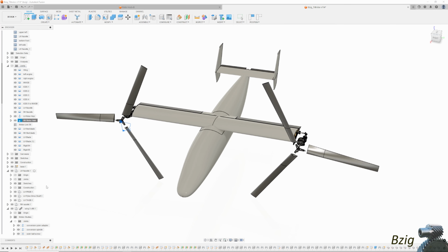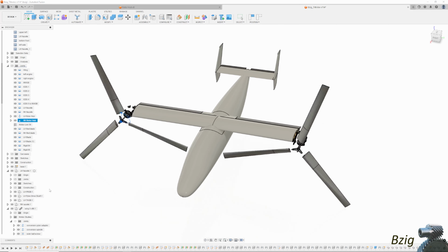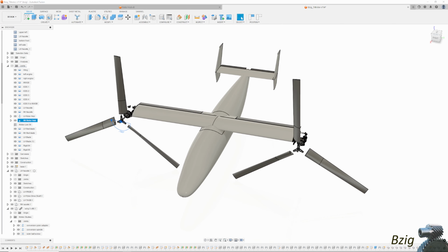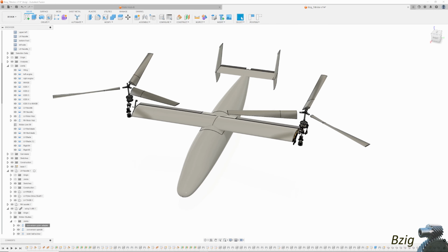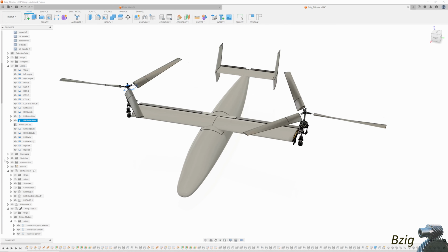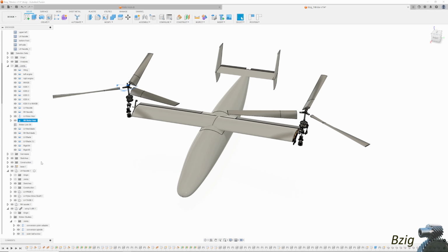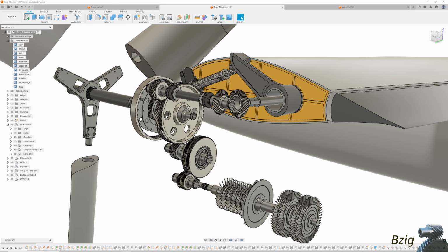A smaller wingspan necessitates smaller diameter rotors, and this means their RPM can be higher without seeing transonic tip Mach effects. My design goal for what you see on the screen was for these rotors to have a tip speed of 70% Mach 1 at standard sea level conditions, and this worked out to 506 RPM with a 59-to-1 gear reduction from the engine to the rotor.